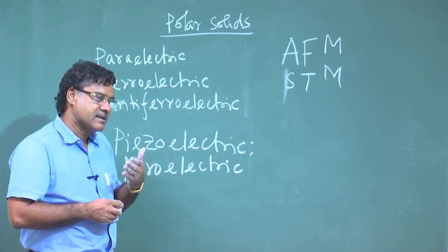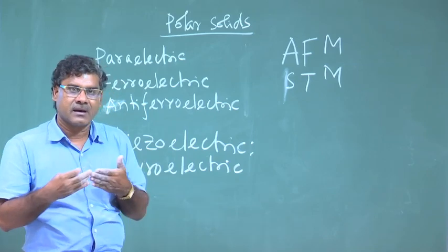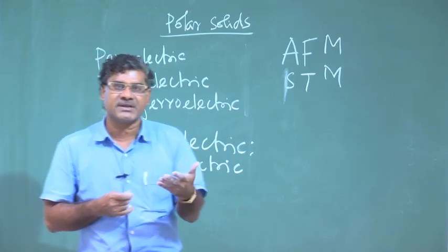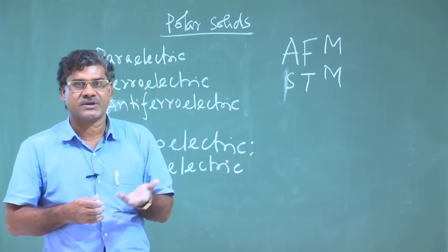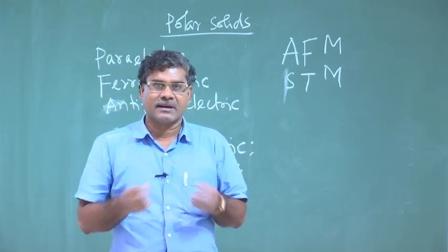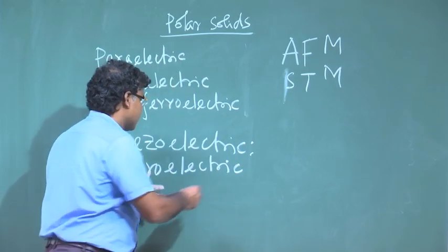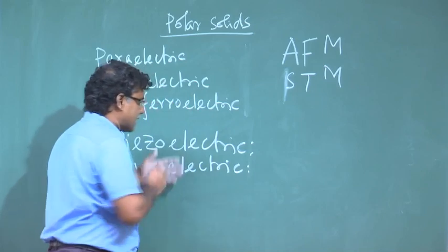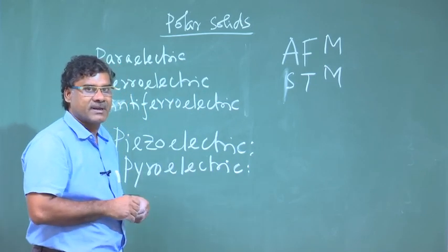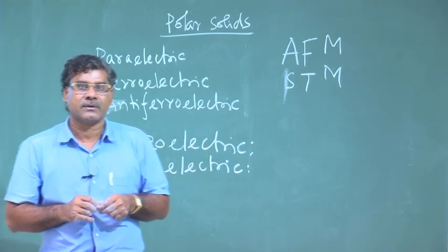When temperature changes, then it is polarized. Okay. Means again it is giving me charge or voltage, an electrical signal. So, temperature is converted into an electrical signal. Okay. So, that is the pyroelectric material. It is dielectric, but again classified as a pyroelectric material. This material is sensitive to the temperature.